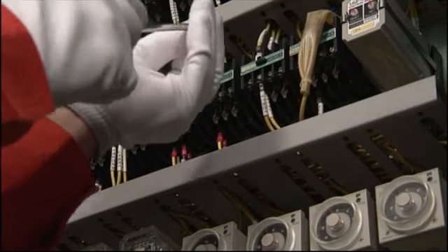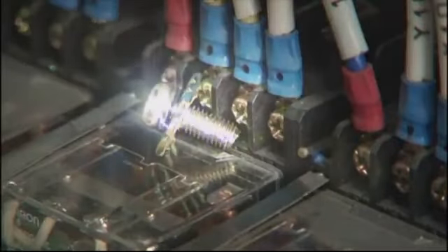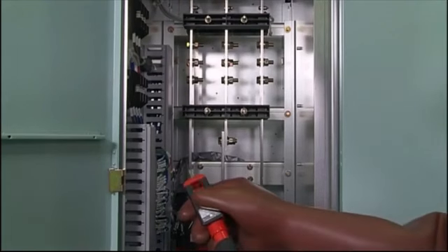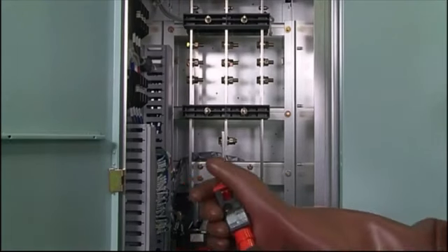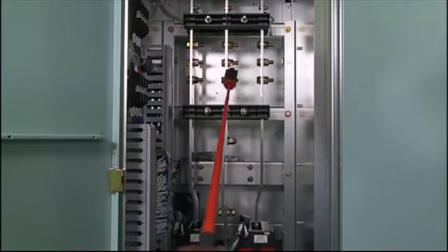Short-circuit accidents can also be caused by bolts or other objects falling onto a hot line. This type of accident can be avoided by shutting off the job site power source before maintenance and inspection work begins. Use an electroscopic bar to confirm that the target is not electrically charged.